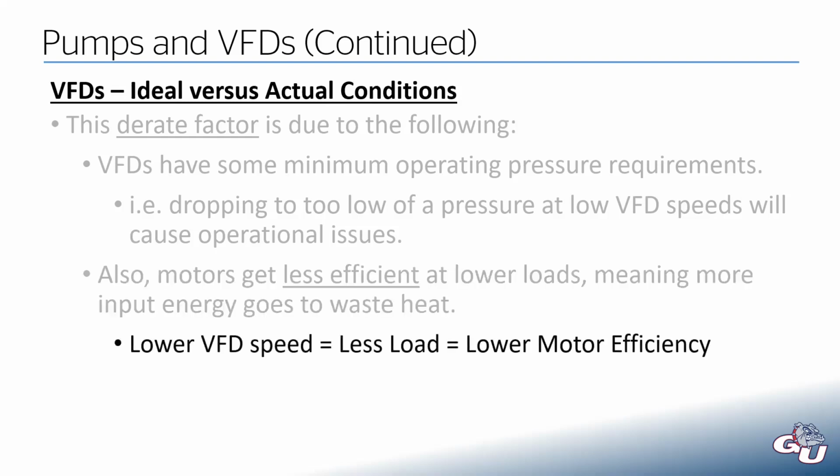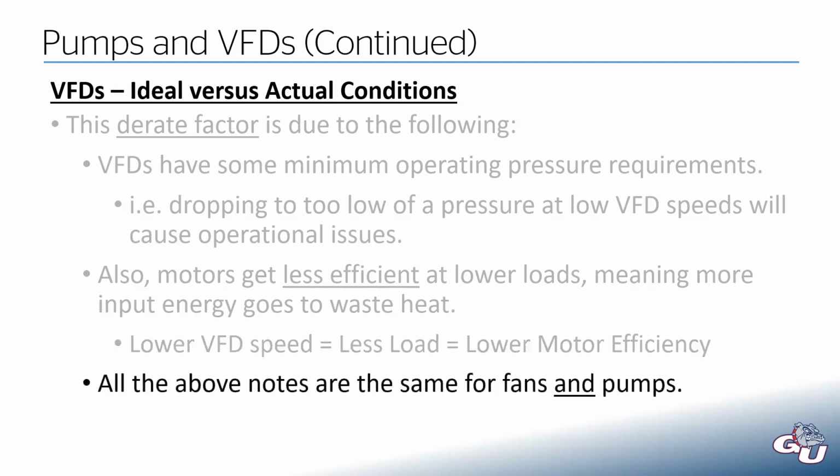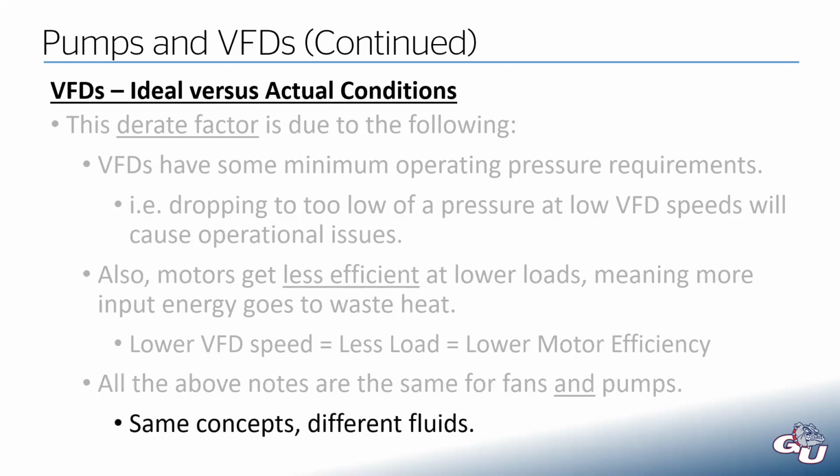So if we have lower VFD speed, that means less load, lower motor efficiency. And this all applies to fans and pumps because, again, just to drill it in one more time, same concepts, different fluids.